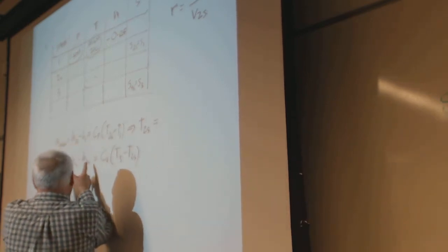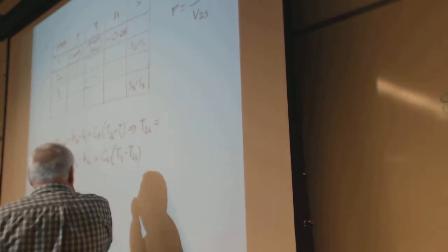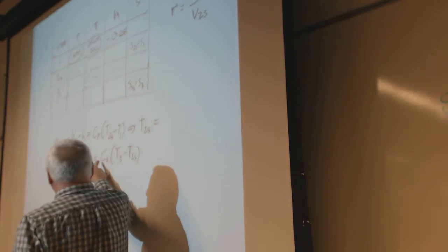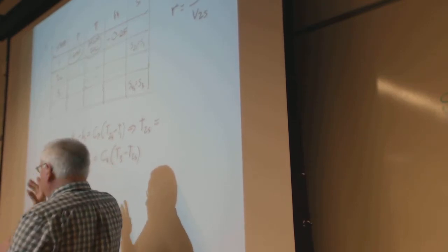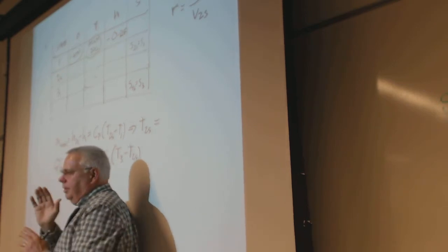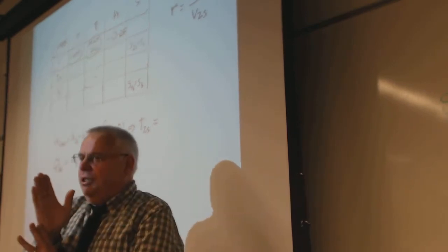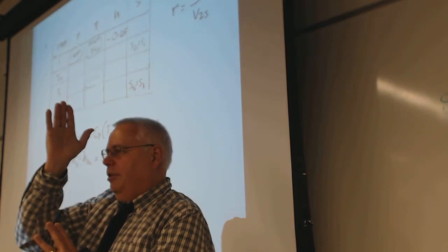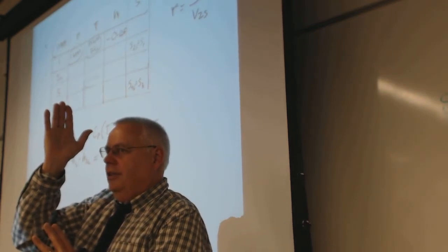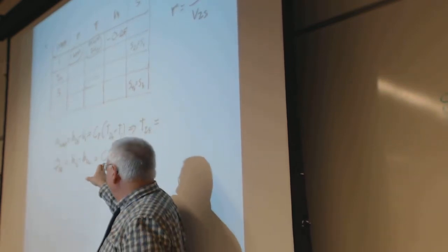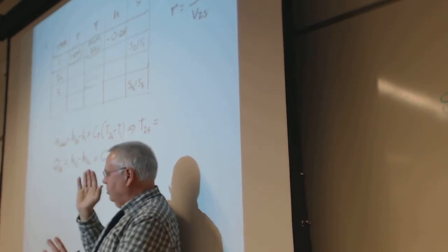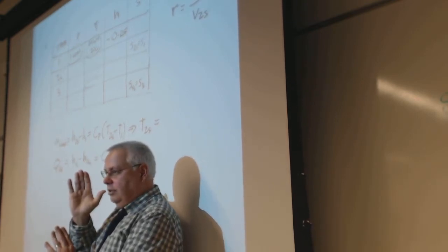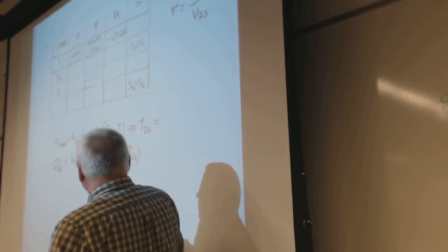All about change in enthalpy, but enthalpy, well, in this case, it's constant volume. It uses C sub P. There's no work going on, so we'll still call it enthalpy. If it's a constant volume, the pressure rose, but that's going to be part of the internal energy. So we can use the C sub V value for this one. It really ends up being a change of internal energy because there's no change in work if it's constant volume.